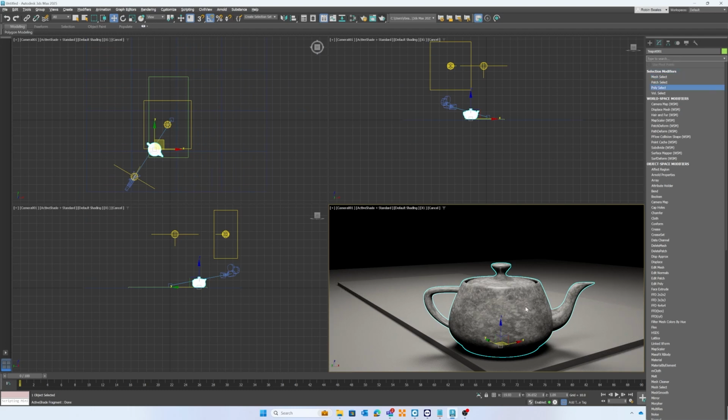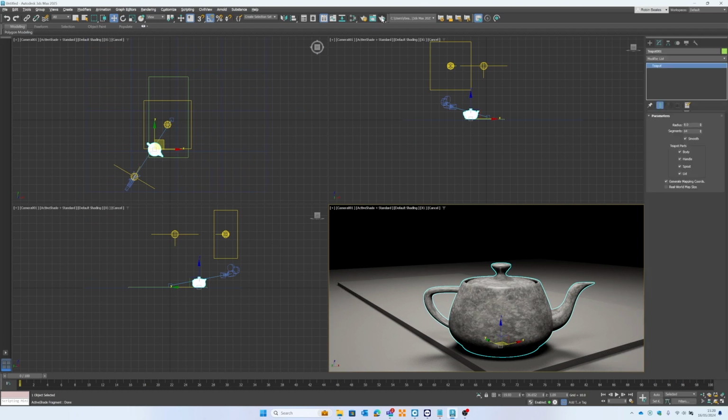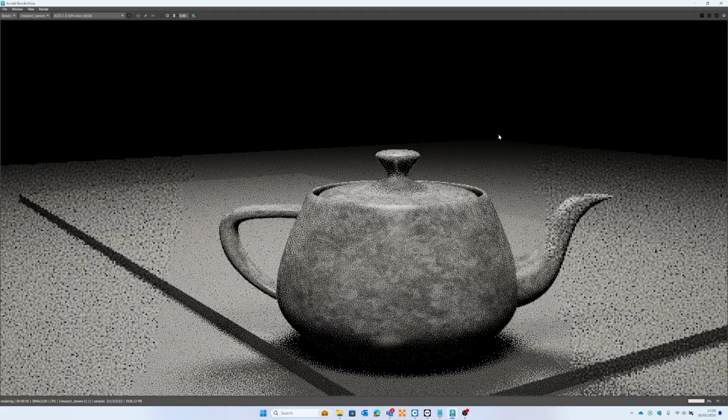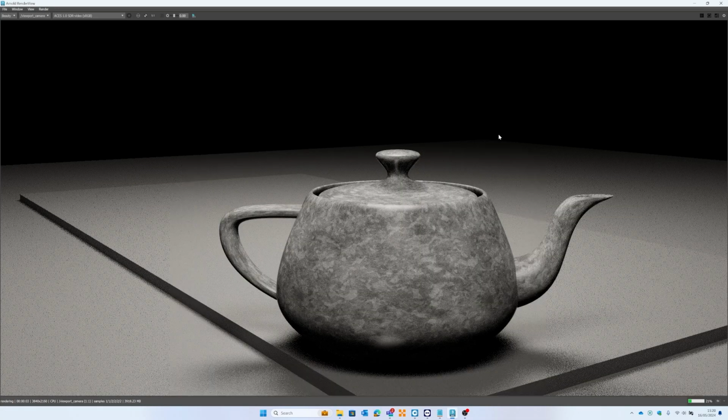But again, go ahead, add your texture on, use UVW map to get it to wrap correctly around the component so it doesn't look stretched around any of the positions. Check out unwrap UVW if you need to. That's particularly good for very smooth and very curved faces.